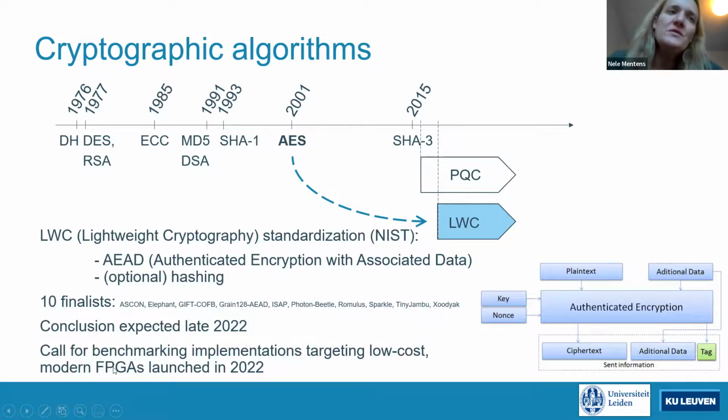So here it's useful to use FPGAs to benchmark these algorithms and to see which one has the potential of being lightweight on an ASIC. But I would not say that FPGAs are necessarily the target platform for end products using these algorithms, or not the main target. There can, of course, be applications where it's useful to also have these algorithms together with some other things on an FPGA. But I'm mentioning it because it might be interesting for you to have a look at this benchmarking effort that is being done at the moment.